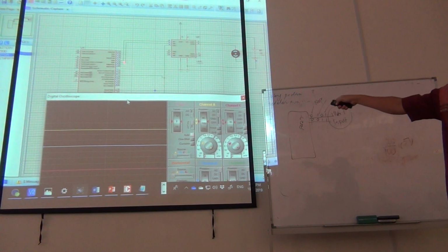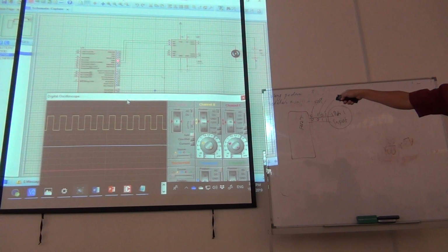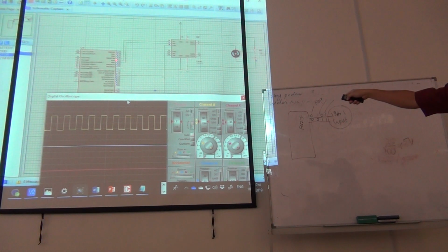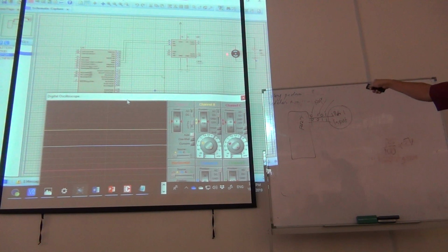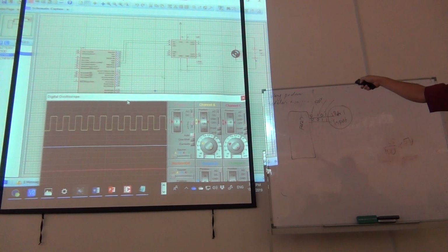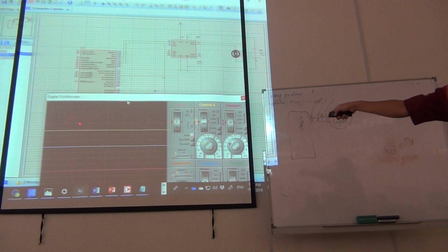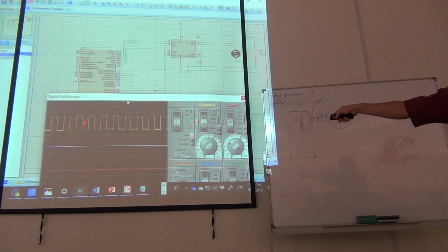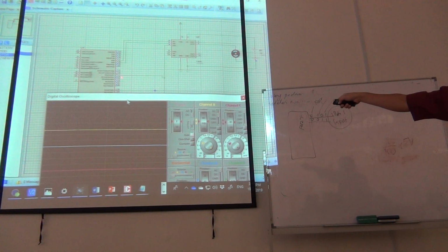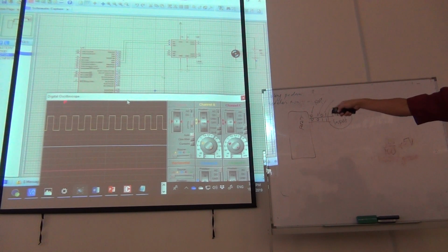My example now, you can see this one, RB4, RB5. RB4 is 1 and RB5 is 0. The direction is over here just now. And then I change RB5 to red and RB4 to blue. The direction is the other side. So you can see my PWM right now is around half of the PWM. The PWM is coming from the CCP pins over here. Okay, so this is the PWM.